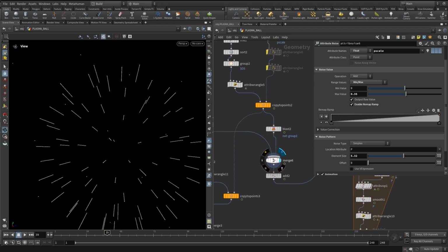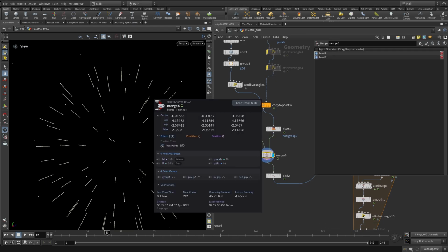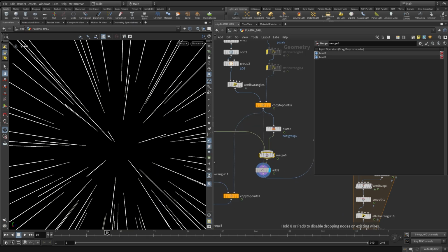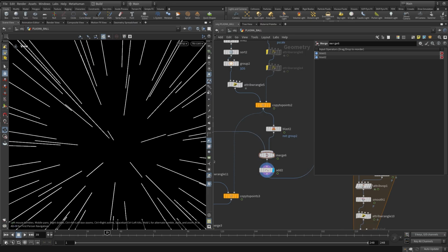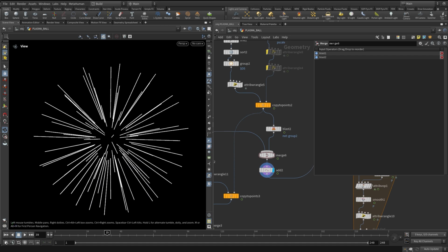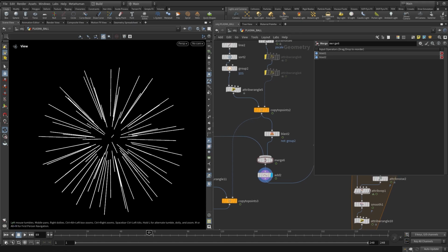Since we have our custom point ID attribute, we can use this as well to connect the points of our small and biggest sphere. And here you can see it has some animation of our pscale that we had assigned.